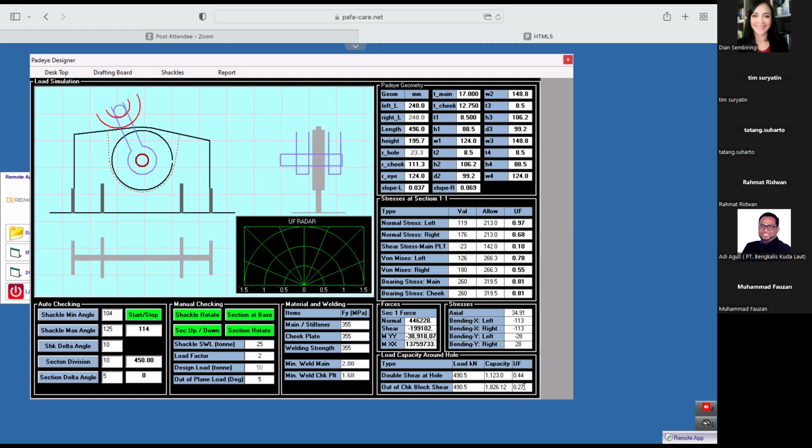So here you can see it's okay, because the utilization factor is 0.27. If we check around this again by running this analysis, I think we should go for minus 4, for 85 to 200, for example. Okay, this kind of symmetrical pattern. So you can see here the critical line is this one, but UF rated is okay. So it means this pattern basically works for all aspects.